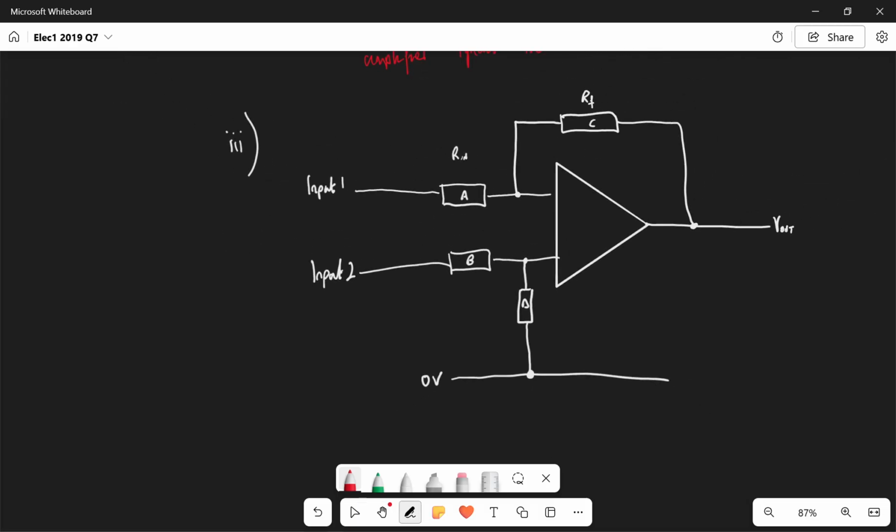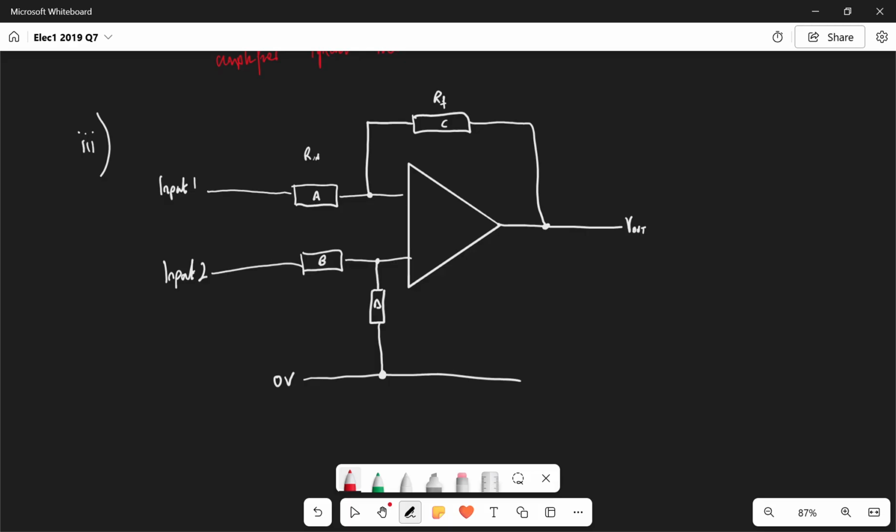Okay, part 3. Now the third part of this question is down to a calculation and a circuit diagram. And it says when a temperature sensing unit output voltage Vout is minus 0.3 volts and the output of the difference amplifier needs to be 9 volts, design a suitable difference amplifier based on a single op-amp. Draw a circuit diagram showing the difference amplifier connected to the temperature sensing circuit. Label all resistors with their values and show all necessary calculations.